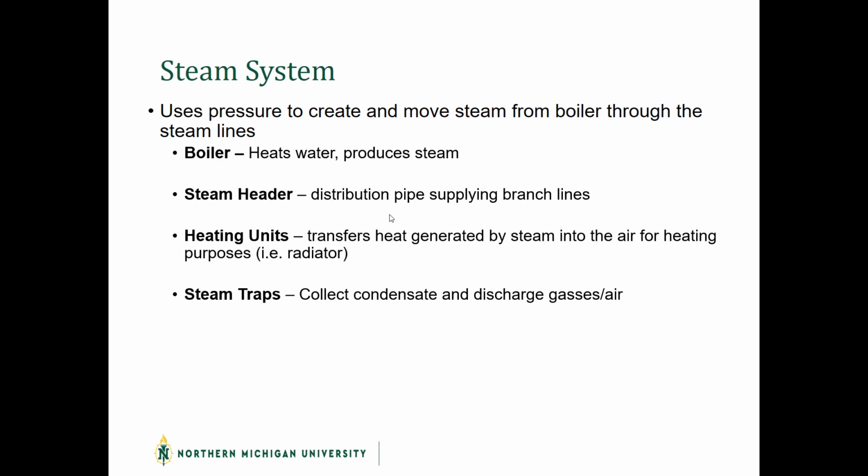After that, once we give off that heat and the system starts losing heat, the steam in there starts to condense. So we need to collect the steam and the condensate at the traps, discharging different non-condensable gases to exhaust from the system, and then collect the condensate and keep the steam trapped in for efficiency purposes and safety. The condensate tank is the next piece of the puzzle in your generic steam system, and that's where we store any condensate that is collected from your system and is refed back in.